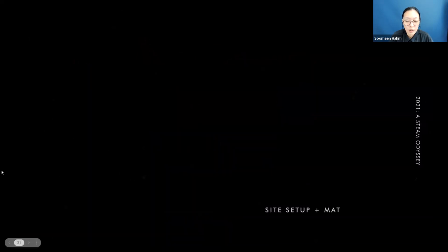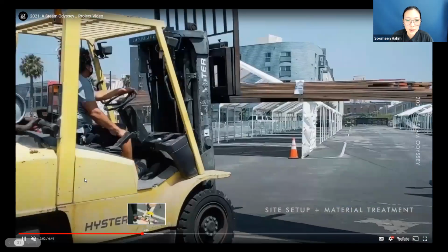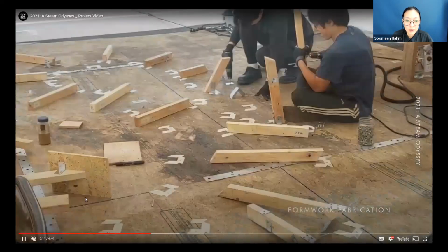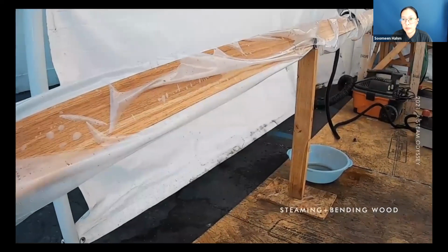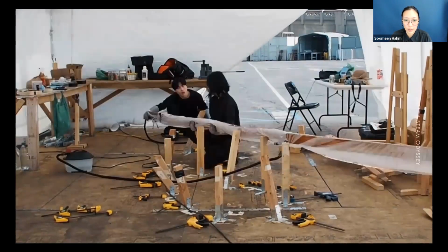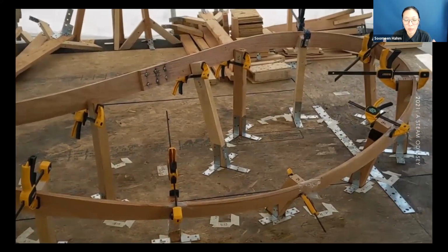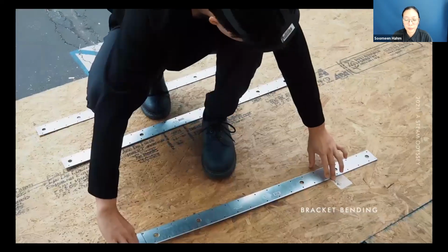We made this into a few chunks and continuous surfaces, connected the raw hardwood materials, and placed these frames using augmented reality to position them in a relatively precise position, and we steam the wood. This is the traditional method of steam bending wood, but normally you need a one-off mold. They have a heavy CNC mold, and you have to bend around it.